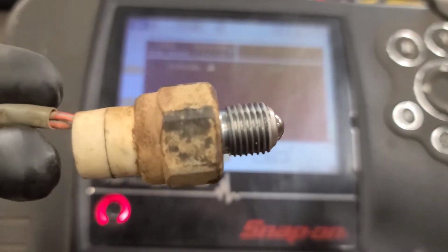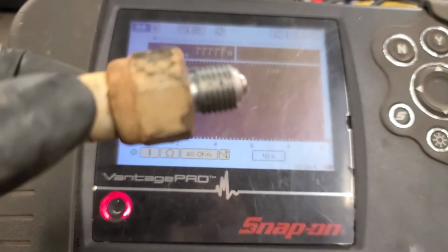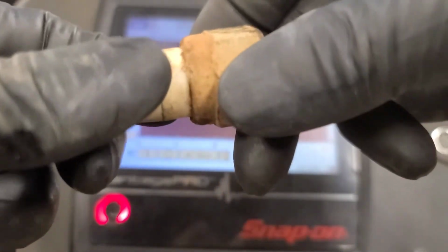So this is the two-wheel drive, four-wheel drive switch out of the transfer case. I can make it work by grounding the wire at the switch. I could make the front axle lock up. So this input to the transfer case control module is not changing state. The switch simply grounds. So I'm going to connect an ohm meter across it and check continuity through the switch.